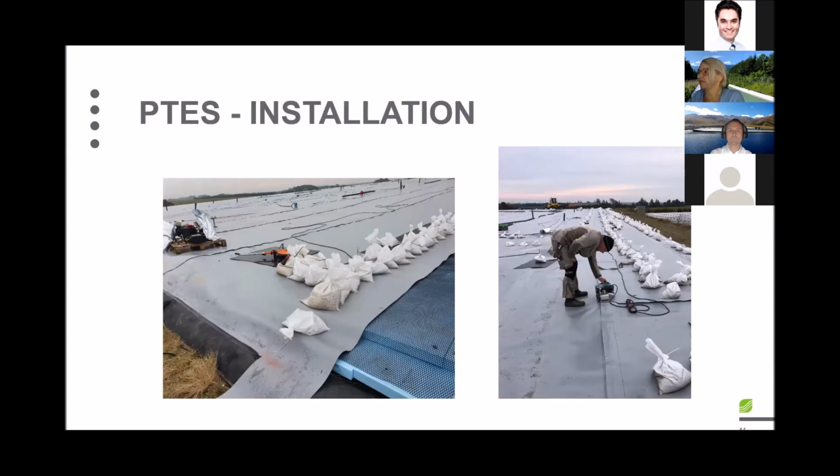After the insulation layers have been installed, the upper geomembrane layer is installed, and as you can see here, a gray geomembrane was chosen in order to fit it into the environment. You can see here the insulation layers below. A key element of that geomembrane is that it has to be UV resistant, because this one is exposed. And it has to have best dimensional stability in order to allow waviness to be reduced. Therefore, a light color geomembrane is of advantage. And it is also an advantage, as I addressed earlier, to have a geomembrane with extremely good dimensional stability, which means it has a low shrinkage and therefore allows it to lay flat. The installation is ongoing with the typical welding procedures here as well.